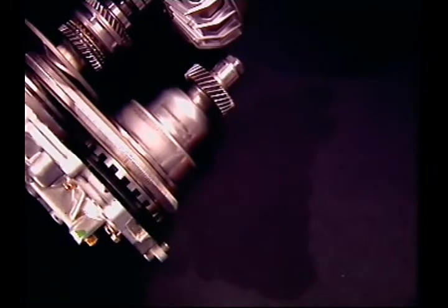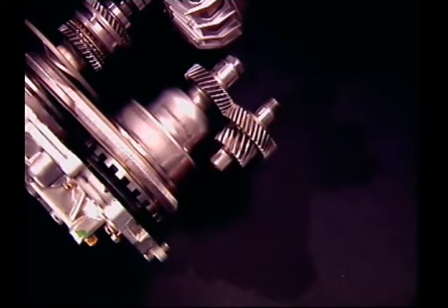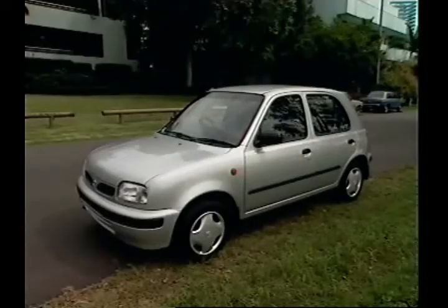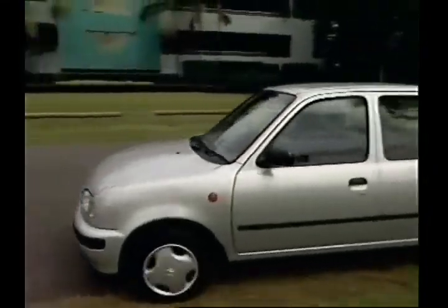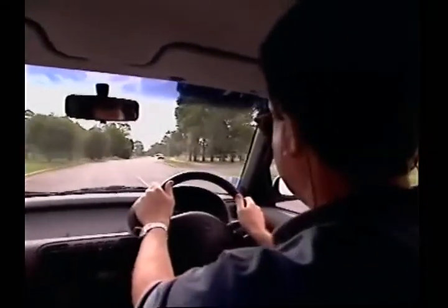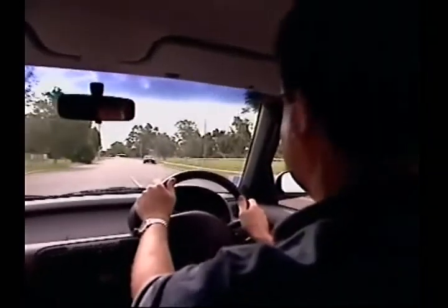The secondary pulley shaft is splined to a helical reduction drive gear. It meshes with a similar reduction driven gear splined to the final drive pinion shaft. The final drive pinion meshes with the final drive ring gear to transmit the drive to the differential case. Selecting D provides a normal driving mode from start-off to maximum speed. Speed change occurs between 1600 and 4000 RPM, depending on whether acceleration is gradual or rapid.